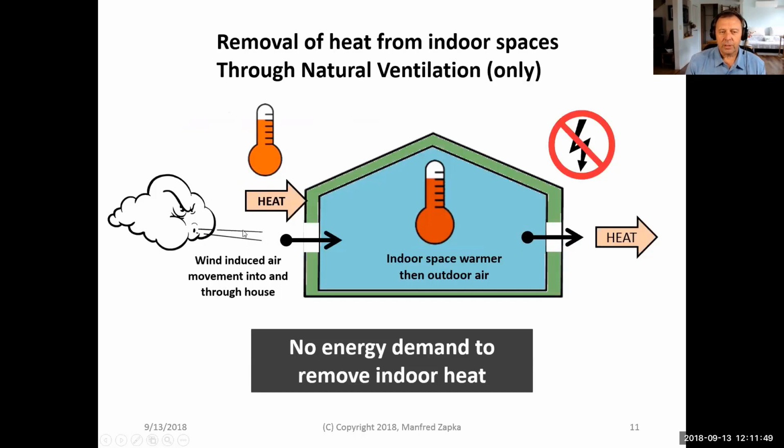It's giving a puff here, it just creates wind. Wind creates pressure on the outside envelope, and therefore a driving force of wind through the building. It could also be something like the stack effect, where the pressure differential is due to buoyancy movement. But right now, let's consider the wind.